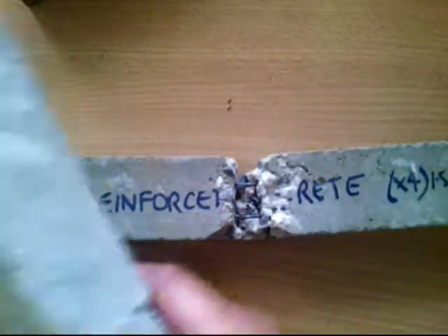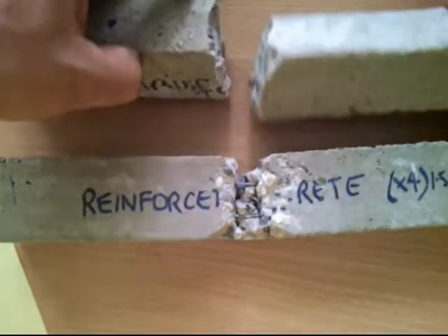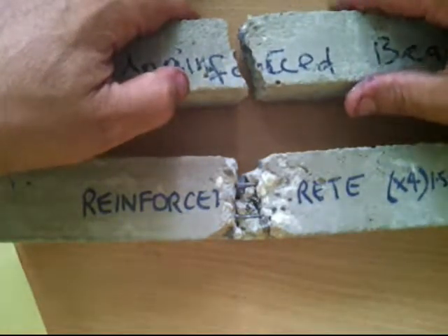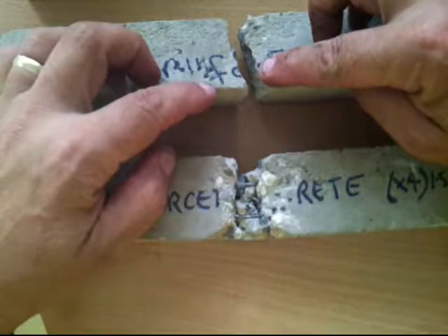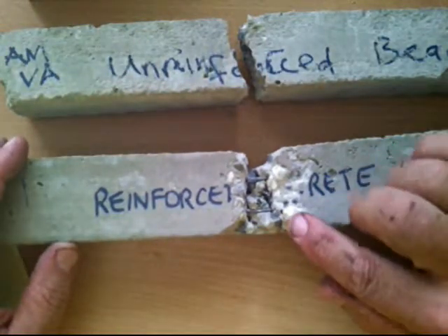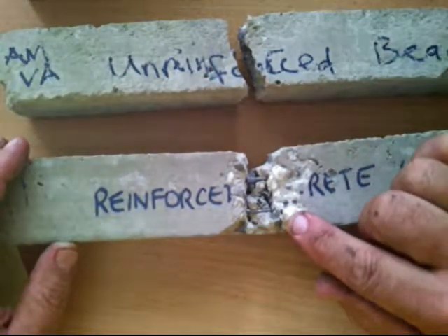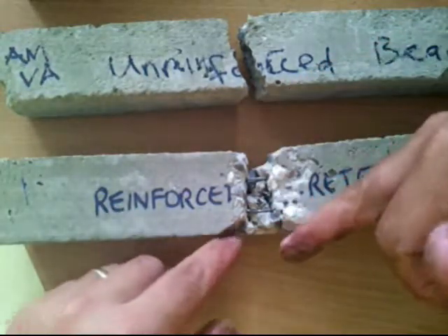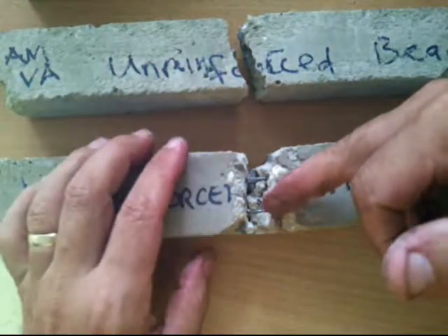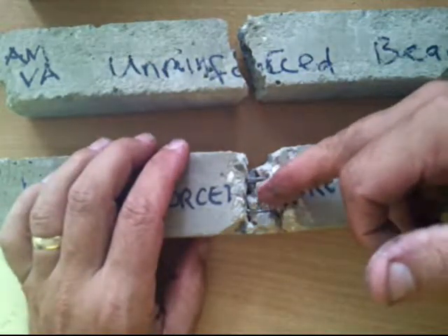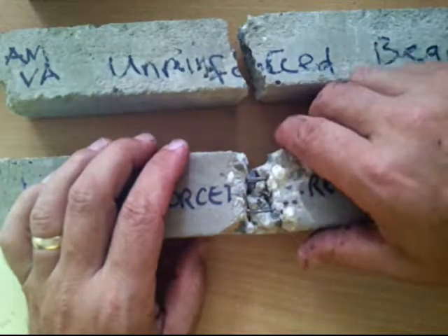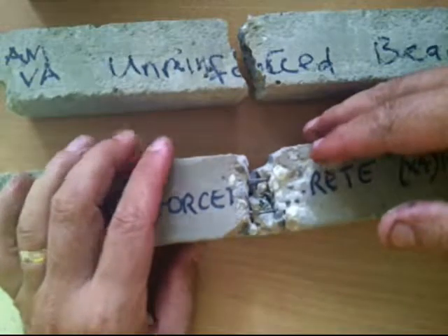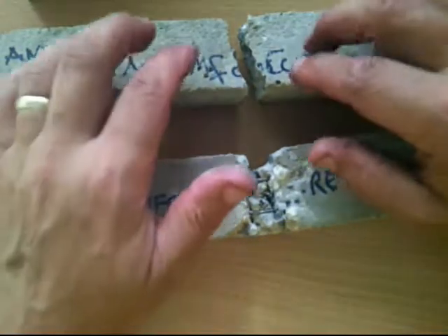Now this beam is quite different from this other one which I showed you a sample of earlier, which was unreinforced. When I put some force on the unreinforced beam here, it cracked very easily, almost immediately, and suddenly. I had to put much more force on this beam over here, and when it failed, it only failed slightly. There was some cracking at the bottom, force coming at the top, so therefore the bottom was in tension and it began to crack, but very slowly the crack started to travel and there was deformation before, and in fact it never even really fractured, it just bent, plastically deformed.